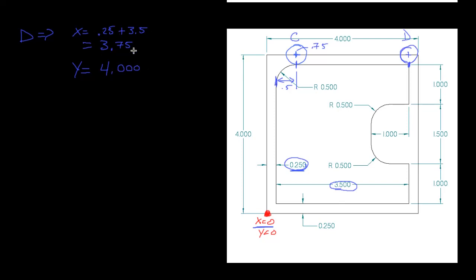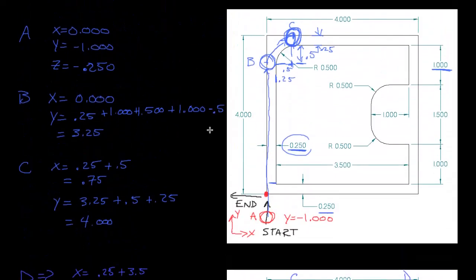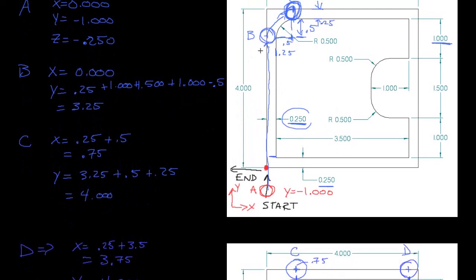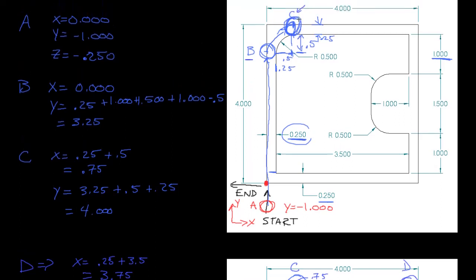Okay. One thing that I didn't do here, and I wish I had, is specify the arc that goes through point B and point C. So point C here. So that's this tool path here, this arc right here in pink. So that arc is going to be basically the radius of the milled part plus half the radius of the cutter.